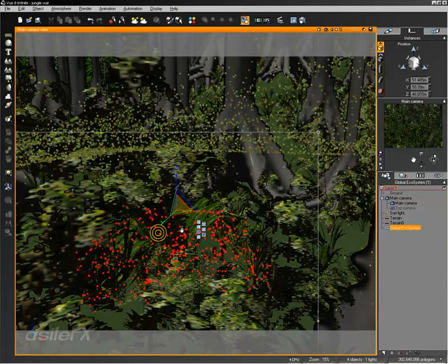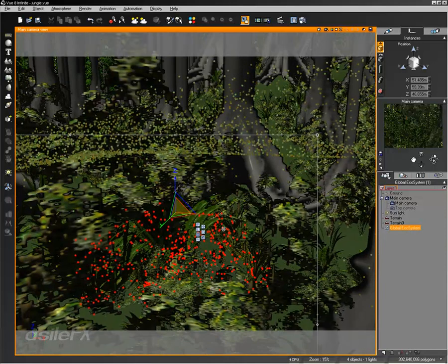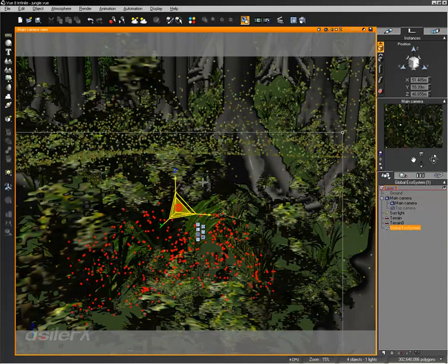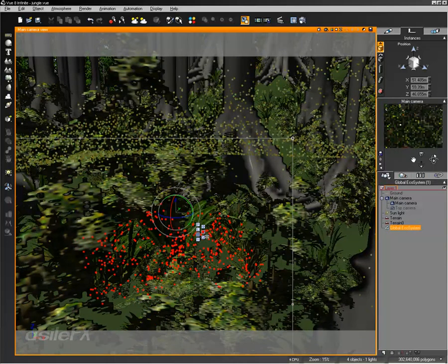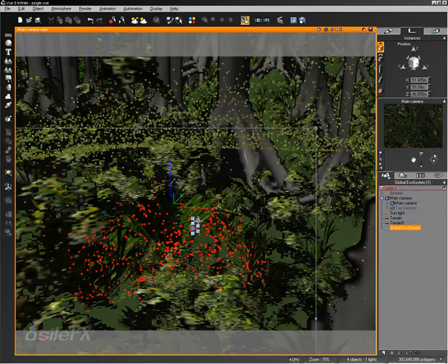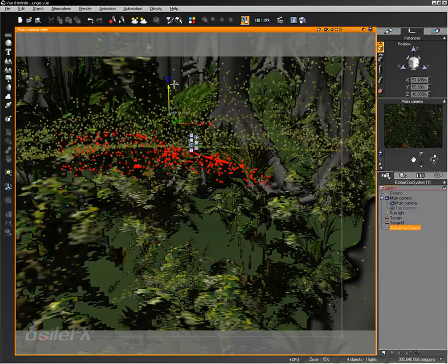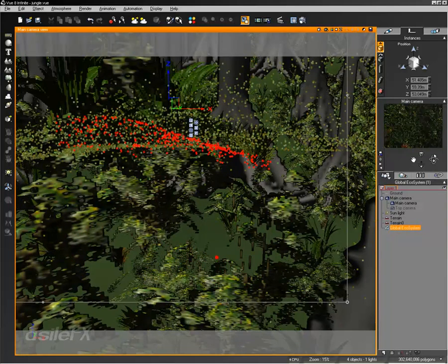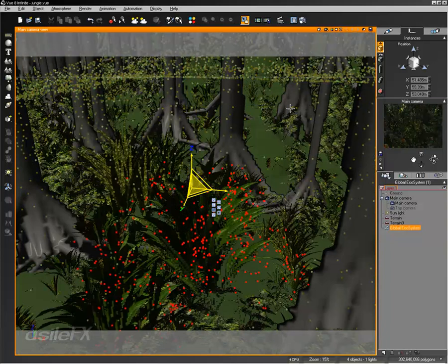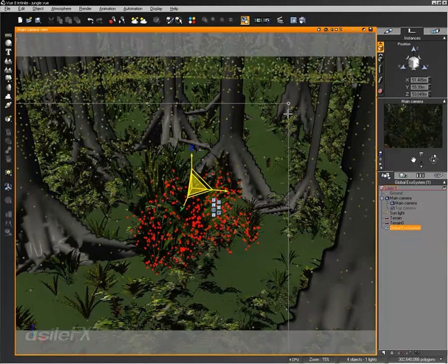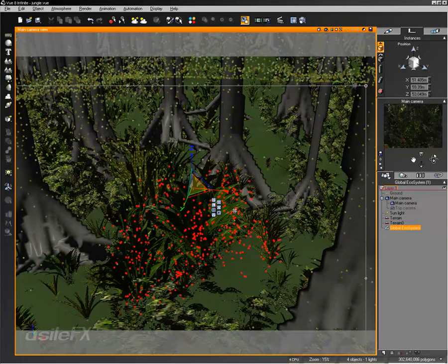This allows us to directly manipulate the instances using the size tool, rotate, and also move. If we want, we could switch to move and move these up into the scene. This gives us a much easier way to directly edit any of the painted ecosystem objects without having to use the ecosystem selector to grab the global ecosystem.